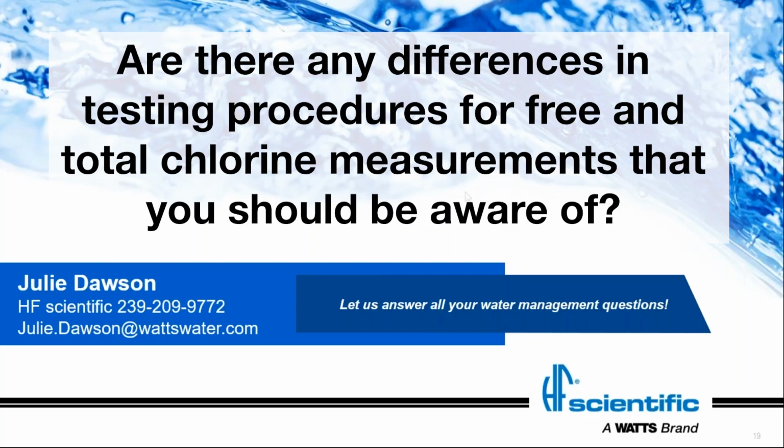Online, it's done very quickly and it's done within that time frame, so you don't have to worry about the online analyzer. But when you're doing the handhelds, you want to make sure that we don't, because commonly I'm multitasking if I'm working in a lab, and I might mix something up and leave it for its reaction time and walk away and then come back and measure it. We don't want to do that specifically with the free chlorine. We want to measure it within the time frame specified by the manufacturer of your instrument.